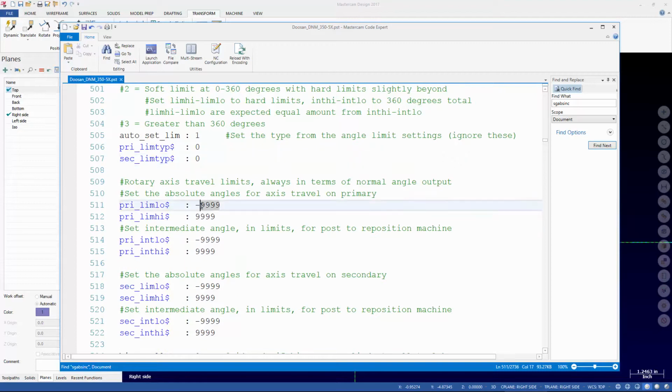But right now, primary, now if we were going to do a live simultaneous cut by just positioning A and rotating C, that's when we need to know if the rotary truly is unlimited and continuous, or if there is an actual limit.